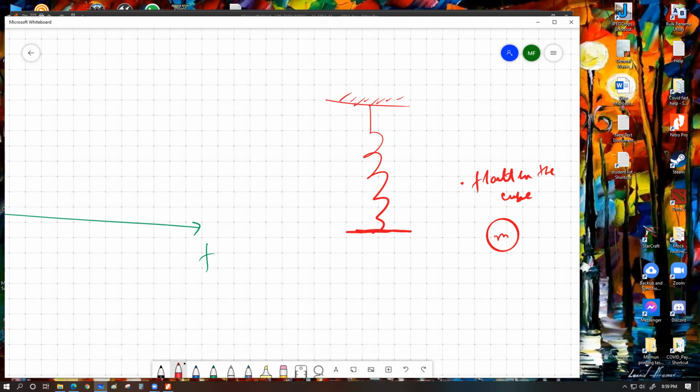And if we now give the hanging metal mass exactly the same initial amplitude and allow the oscillation to go on, it is going to lose energy much faster, because with every single oscillation it keeps colliding with a bigger number of atmospheric particles. So we lose energy faster, which causes the amplitude to drop much more rapidly. This is one way where we are not changing the mass of the system significantly. And because we are not changing the mass significantly, the natural frequency would still remain the same.